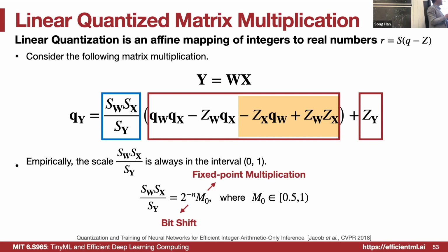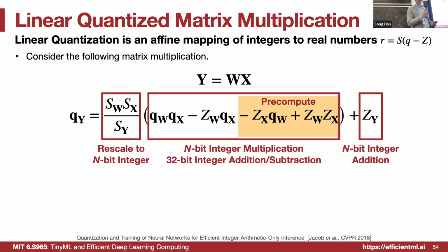So there is a very simple function in the library that can help you do such decomposition. So actually, you can use integer multiplication. So this is the integer. And then you can actually do bit shift, since 2 to the power of n can be easily implemented by shift, so multiplying with this scaling factor doesn't even require floating point arithmetic. So all integer arithmetic can deal with this problem. And so with that, let's continue the discussion.